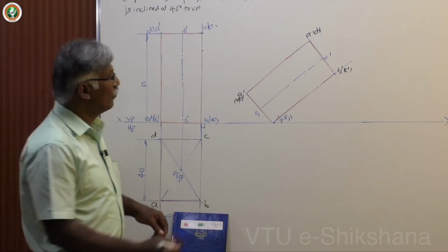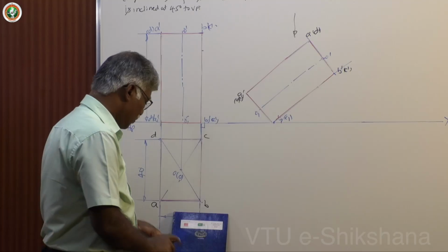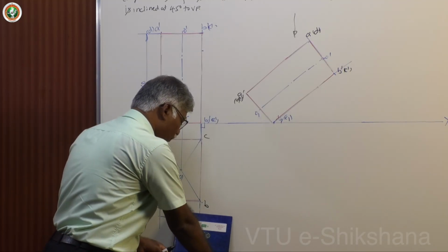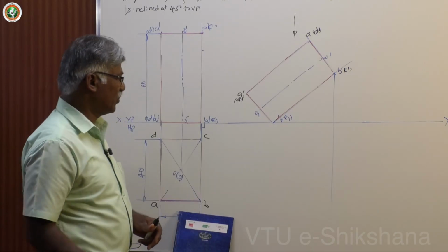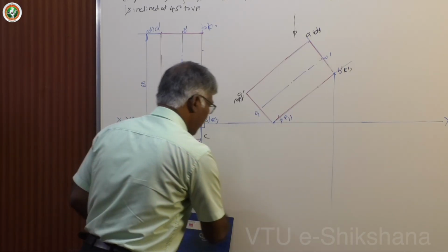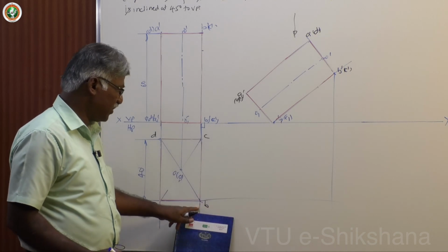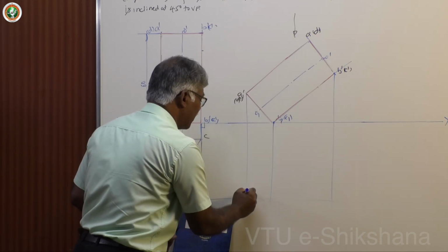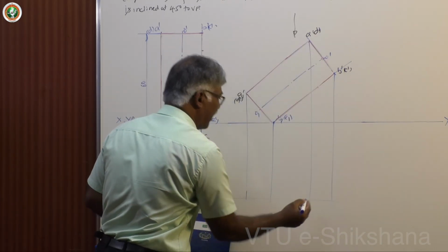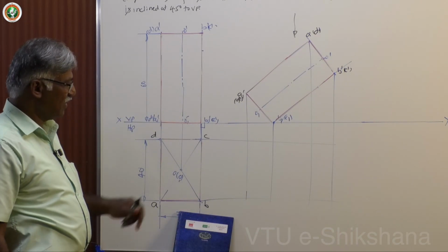Now we are here. You have to complete the top view. So as usual, you draw the rightmost projector from the second figure front view and bottom line from this point projector. Then these are the projectors. You should not go beyond that. Then draw this. It's very easy.